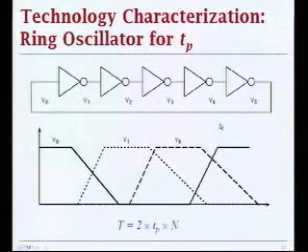This is really a good circuit to give you a first-hand understanding of the capability of your technology. But when you calculate a propagation delay of this inverter in this configuration, it's really not a very useful number, because you can calculate, for example, a 20 picosecond delay. That doesn't mean that your design will be able to work at 50 gigahertz, because there are many other things that affect the speed of operation at the higher abstraction level.